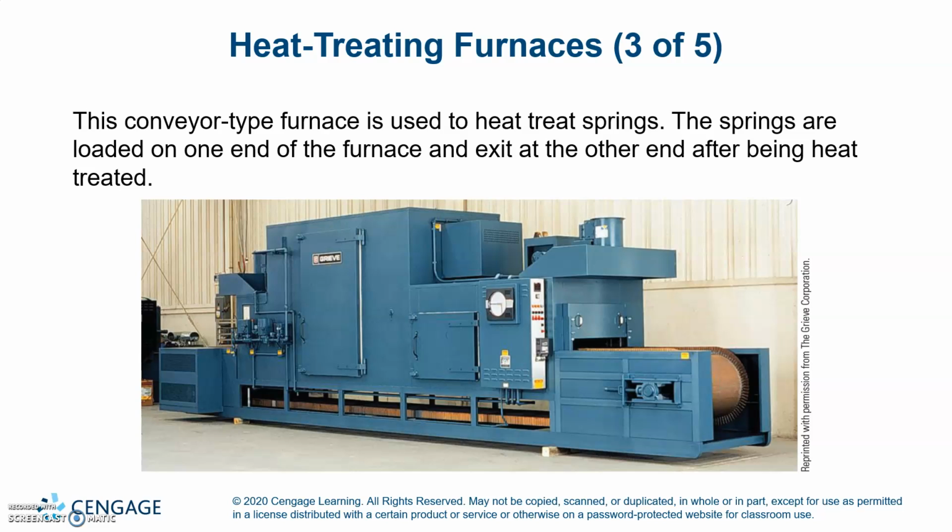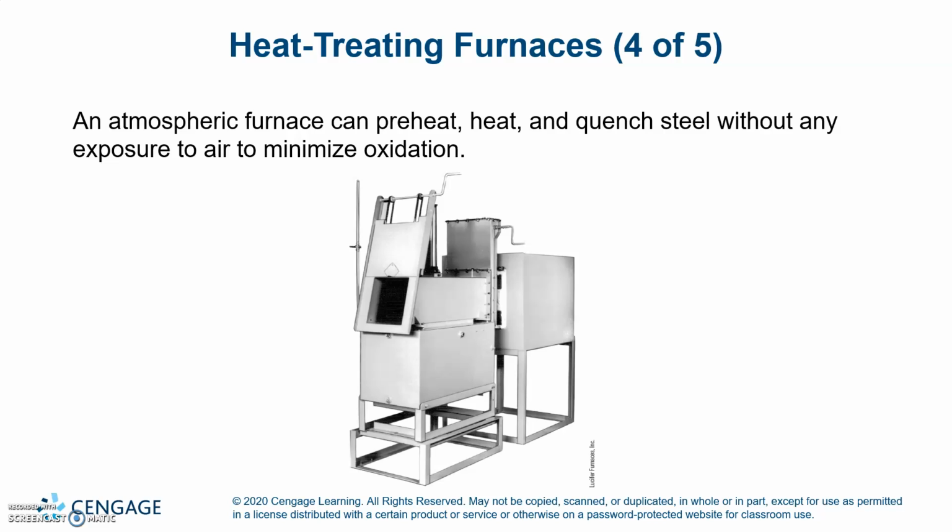This conveyor type furnace is used to heat treat springs. The springs are loaded on one end of the furnace and exit the other end after being heat treated. An atmospheric furnace can preheat, heat, and quench steel without any exposure to air, to minimize oxidation.